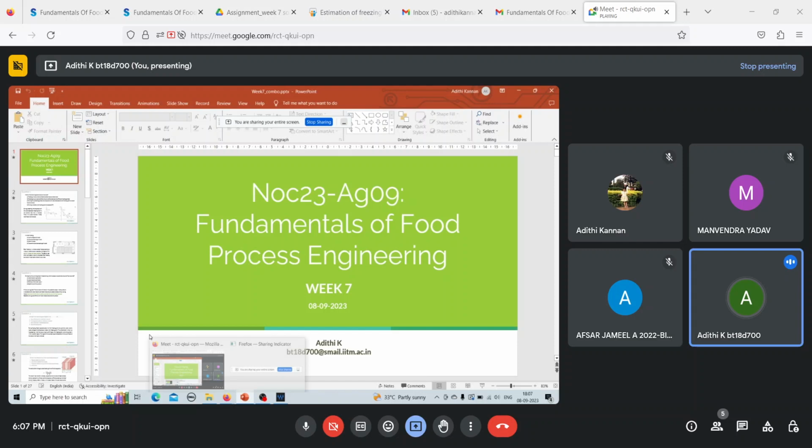So this is the pre-cooling stage, this is the post-cooling stage. So in food you see that there are multiple other curves that are involved. It is not as straightforward as the pure water. This is because food materials will have a lot of solutes as well along with the water content. So from A to S, you will see sensible heat being removed, where you will get the super cold food. This is where the ice crystal starts nucleating. Because of the nucleation, you will have a slight removal of latent heat, which increases the temperature back to the freezing point, which is point B.